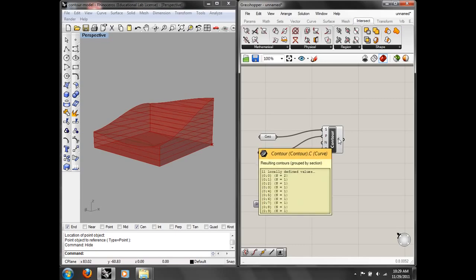And if I had a topo that was going up and down and I cut through it and I had two pieces of it, those are going to be inside of the group here. So you'll see like N2, N3 or whatever. You want to watch your data structures so you keep things in those groups. Otherwise, you're going to have these little pieces just floating out there and you don't know what group they belong to. In my case, though, this is relatively simple, so it's giving me one line for most of my contours.